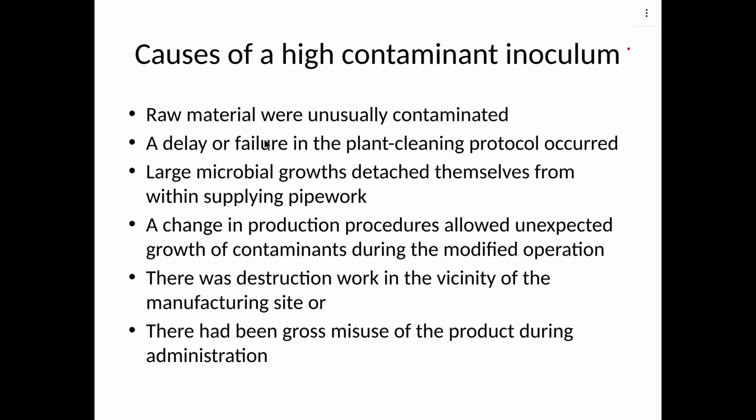So that's what we are talking about here. Large microbial growths detach themselves from within supplying pipework, okay. So some of these huge companies will ensure that there's always water flowing, so that at no point will you have a dead leg, such that in case of colonization, the microorganisms are able to detach and contaminate.